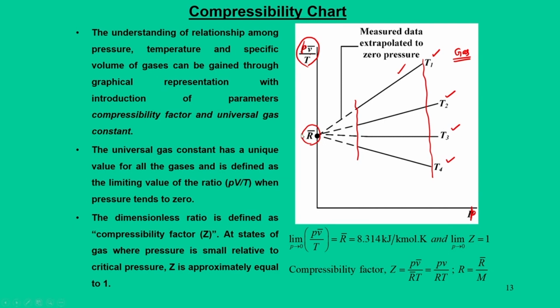So, that means similar plots can also be generated for different gases. It happens in situations where there are a lot of gases, many pure substances. In such cases, instead of drawing this particular graph for each gas, people have used the concept of non-dimensionalizing. With this philosophy, we represent this graphical concept as a compressibility chart.